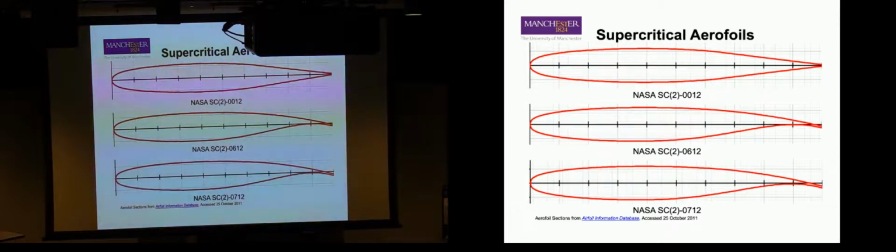And if you ever fly generally a low-cost carrier and you board from the ground where you go up the stairs and you have to board from the rear door, you tend to walk around the wing. Look at the trailing edge of the wing on your A320 or even your 737s, and especially if you fly on, say, a 787 or an A350. If you look at that trailing edge, you'll see there's a lot of curvature in that trailing edge, and that's because they have supercritical airfoils.